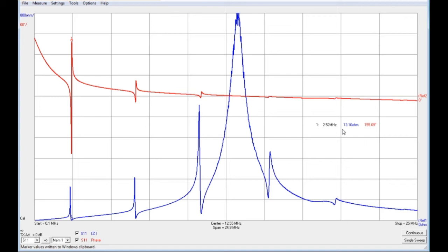So, the secondary seen through the coupling of the primary. We have to remember now that we are looking at the secondary, but we are not connected to the secondary directly. We are coupling through the primary, and that of course has a very big impact on what we measure. When we take measurements like this, we are effectively looking at what the generator will see. So this is the impedance relation that the generator will see.